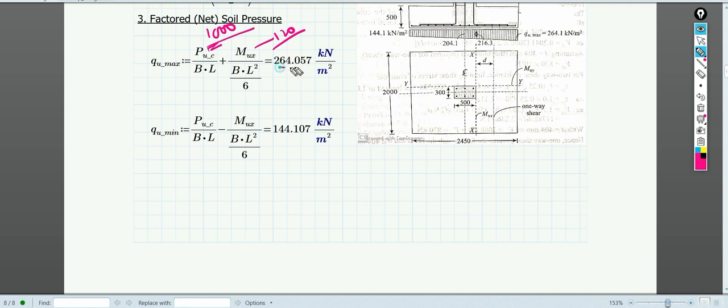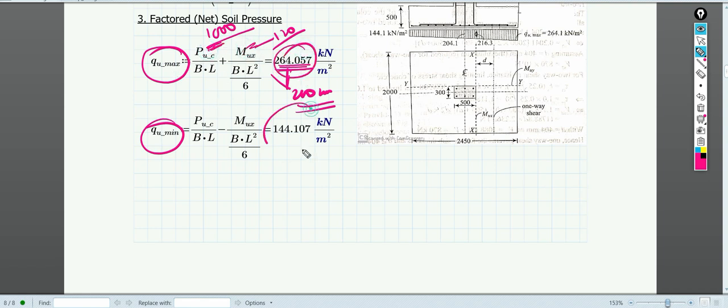And also from the stress value you will see that it is 264, which is greater than 200, which was the safe bearing capacity. Okay, so don't confuse. While we are designing, we have to consider the design shear stresses or the design stress distribution. So here we will be using the design loads, because this will be used for designing.